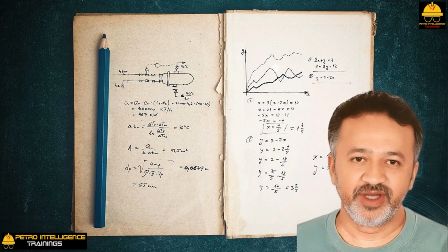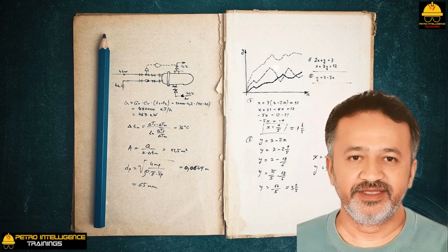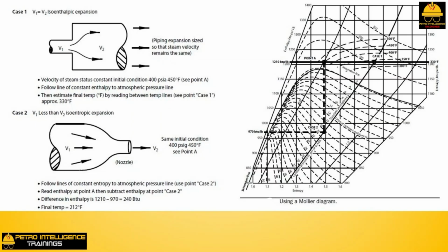Where does all that extra kinetic energy come from? Some comes from a further reduction in the temperature of the steam. That is, the steam temperature will drop from the 440 degrees Fahrenheit supply temperature down to 212 degrees Fahrenheit as shown in picture. However, most of the extra kinetic energy of the steam comes, not from the sensible heat, but from the latent heat of the steam. To be precise, 10% of the steam will condense to water. We can extrapolate this concept further.